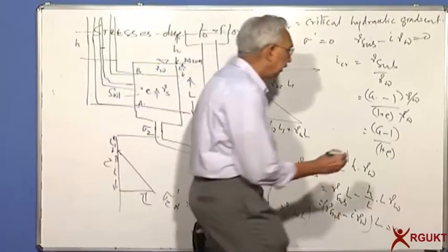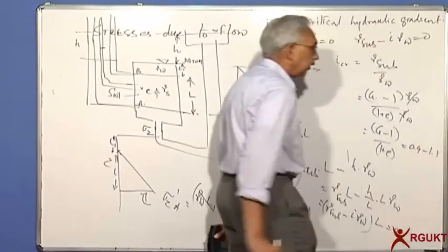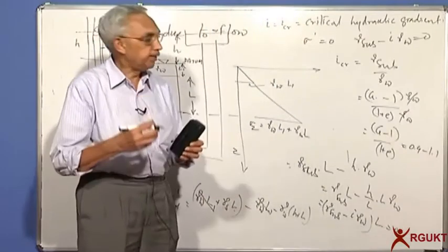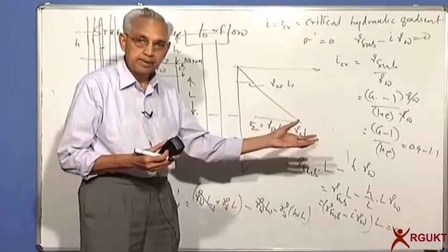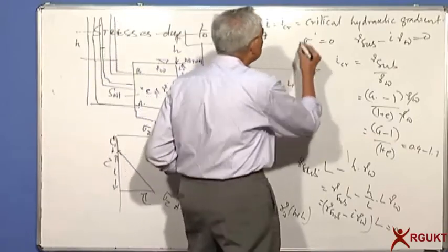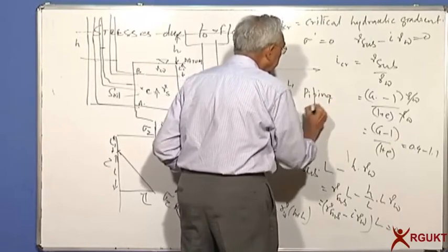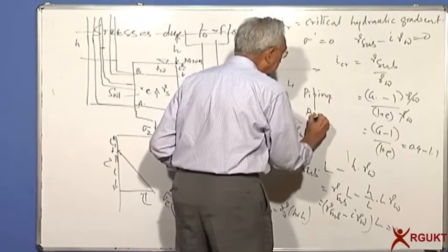It is usually in the range of 0.9 to 1.1, and if the upward gradient is of the order of around 1, the soil will start getting lifted, and this phenomenon is called piping, or you can say soil starts boiling.